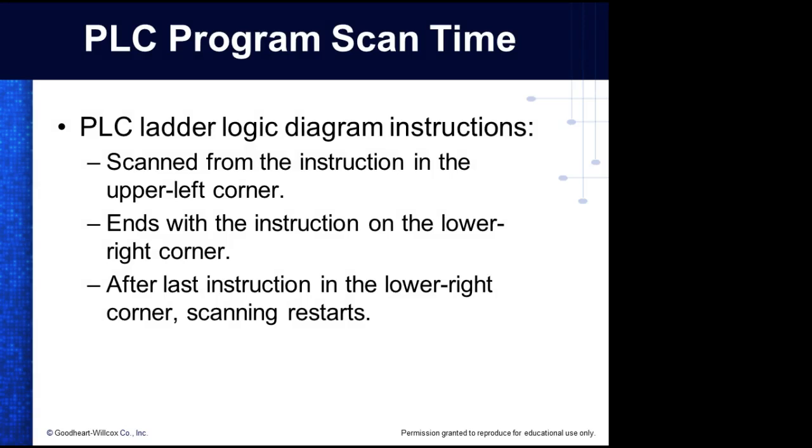Scanning from the instruction in the upper left corner, so upper left corner down, right? So it looks at the input, runs it through the PLC logic, updates the output. Actually, it updates the tables.